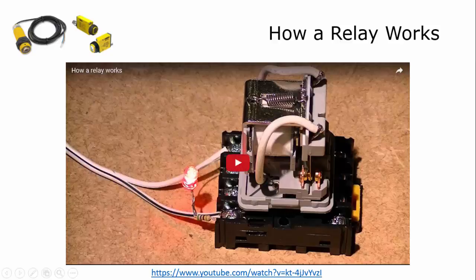And just as a reference point, you can see on this one, here is the coil, and these are the connections to the wiper, to the pole. So you could see the pole or the movable armature here, and these are the fixed contacts. When this coil is energized, this movable armature will move away, because right now it's energized. You can see the LEDs lit, but this will be explained, and this will move back and forth to open these contacts and close these. So let's watch this video.